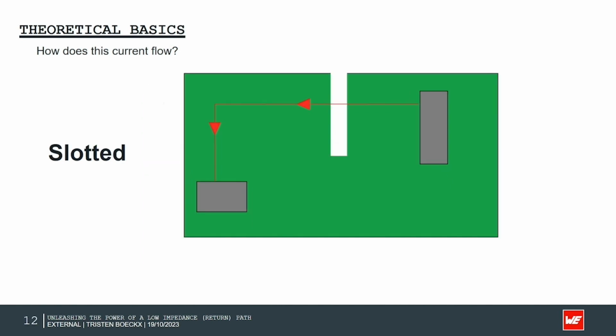When then facing a slotted ground plane, the return current wants to retain the shortest loop area below the signal path. When facing the slotted area, it will flow near the edge, which can create problems in a later stage looking at EMC.